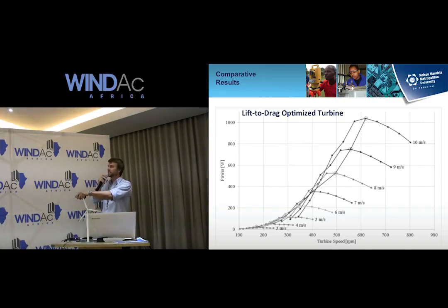So what would happen here if we're optimizing for gusty and turbulent wind conditions? If I'm operating at 8 meters per second, at my max power point, operating at 500 RPM, and there's a gust up to 10 meters a second, boom, I'm now not operating on this line, I'm now operating on the 10 meters per second line. So I'll jump up to this curve here, and I'm operating there. Whereas if I increase my RPM, I could have been operating there. But that gust is instantaneous, so you can't increase your RPM. It happens, and so you jump from there to there.